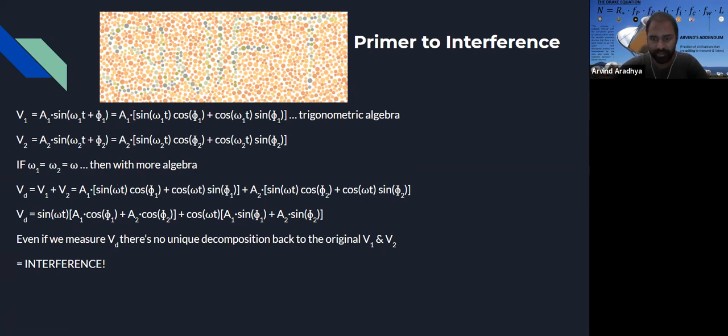The interferers here are active transmitters. Things like radar, things like your phone, which are actually sending out electromagnetic waves, tend to populate the same space as the emissions coming in from space, and then everything gets mixed up at your receiver, and you're not able to tell which is what. This is primarily a problem for people doing passive observations, such as radio astronomy, because the signal strengths there are so much weaker, since these things are coming from light years away.